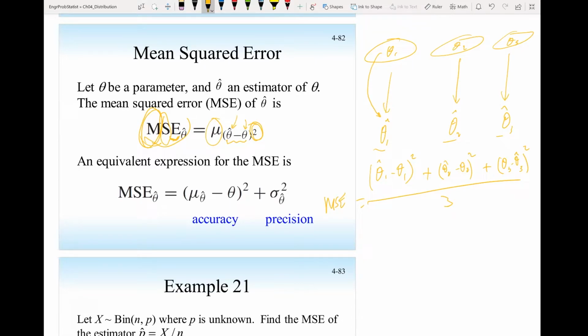And that is a measure widely used in estimating a signal. For example, you may have an image and you have these pixels in the image of value. Sometimes you send the image, it gets corrupted, then you have to estimate the corrupted pixels. Somebody else comes up with another algorithm to estimate the pixels, and you want to see which algorithm is better. So you apply the mean square error. That means you find the difference between the actual image that was transmitted and the image received after you do error correction. That means estimation of corrupted pixels. And you find the mean square error for both algorithms, and you decide which one is better.